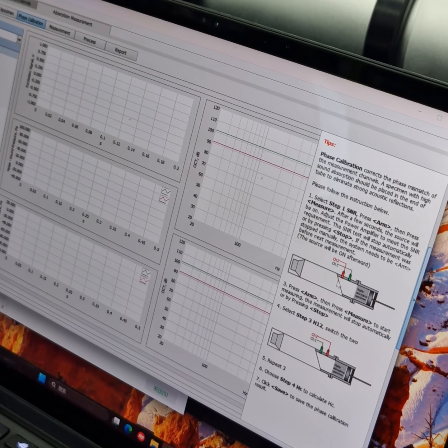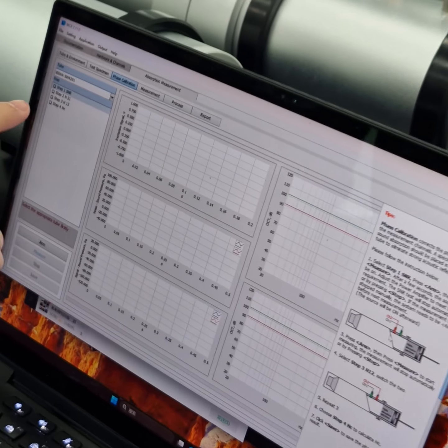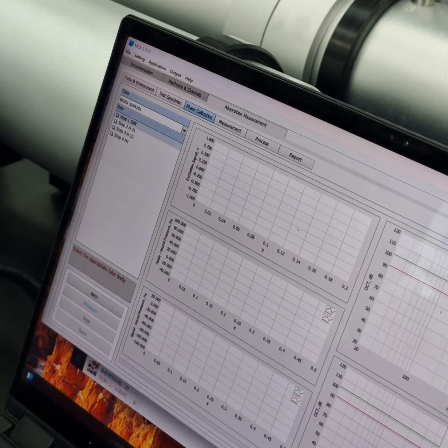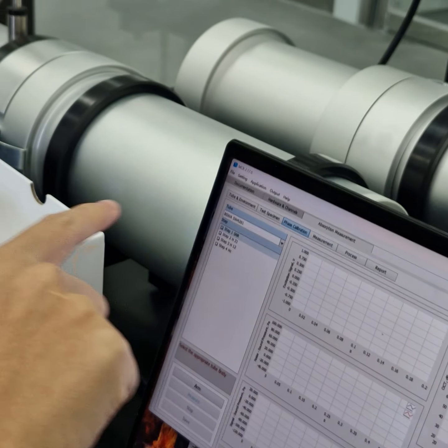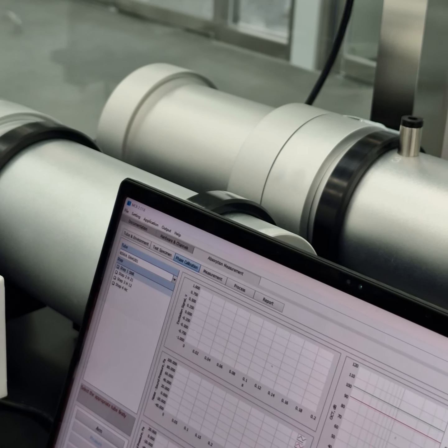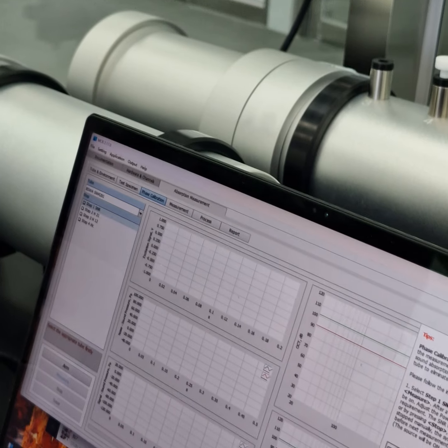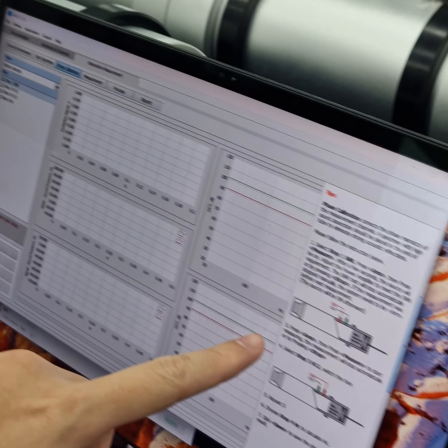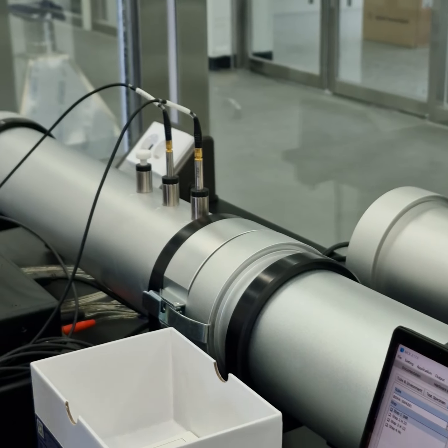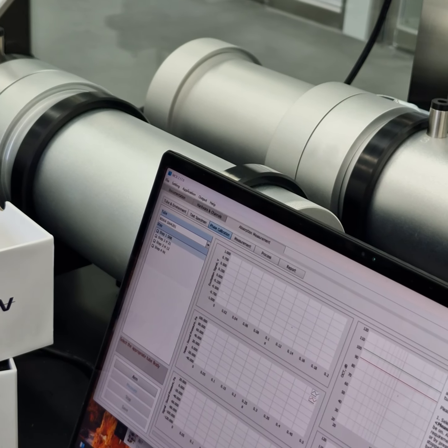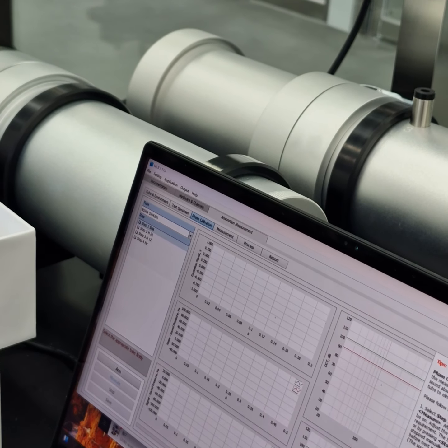See, the first step is measuring. Step 1 is measuring SNR, the signal to noise ratio, and step 2 is measuring H21. H21 means you need to change the microphone first. And here is the diaphragm of H21. The number 2 channel is closer to the speaker. I will show it later. Let's do the signal to noise ratio first. Then we need to turn on the amplifiers.